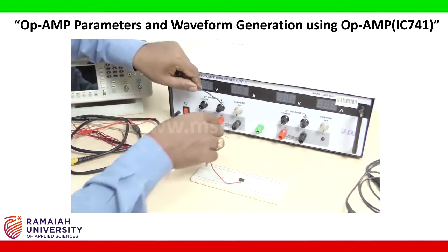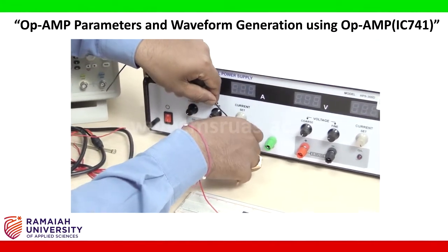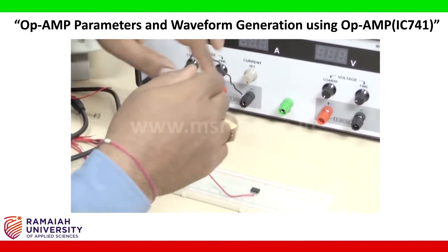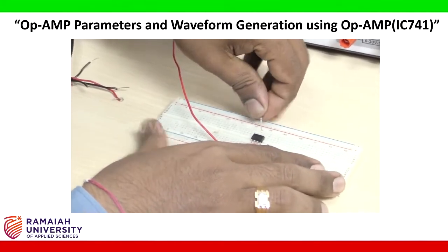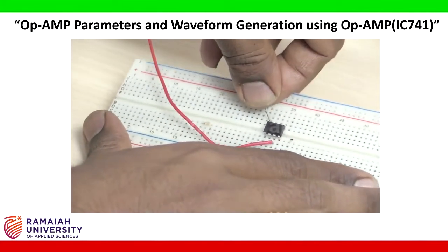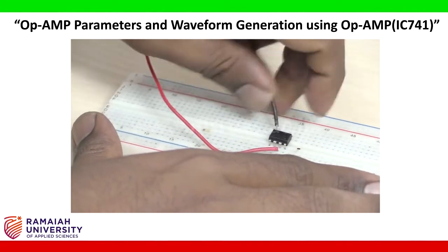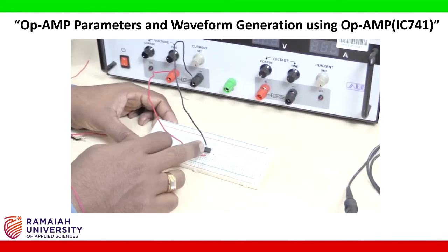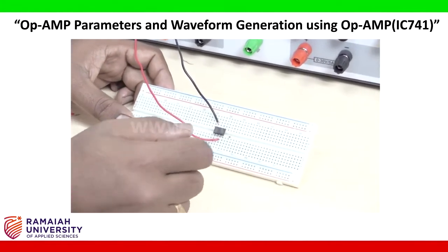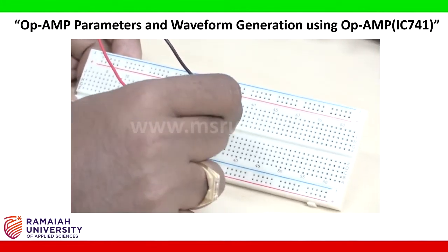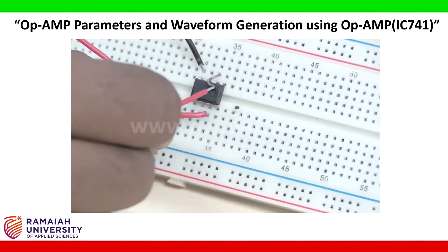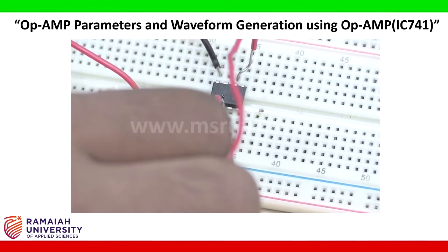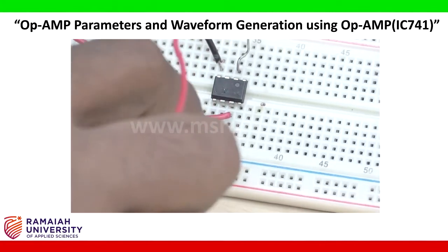Now I am going to connect this negative terminal to pin number 4. Okay, this is pin number 4. I am connecting here. The connecting wire to make the uA741 IC a closed loop circuit. I connect this to pin number 2. This is pin number 2 I connected, and to pin number 6. This is pin number 6. I connected that into pin number 6.